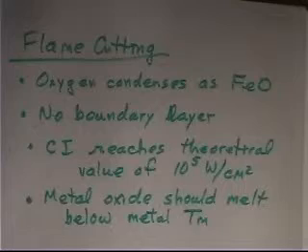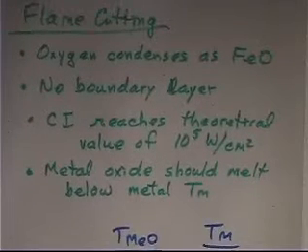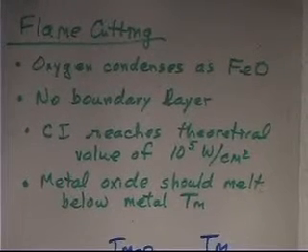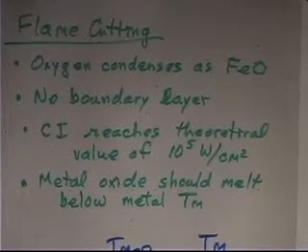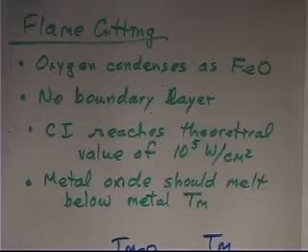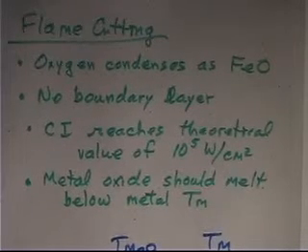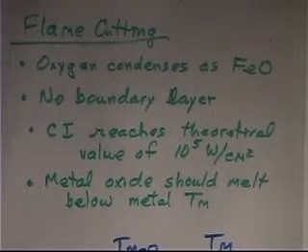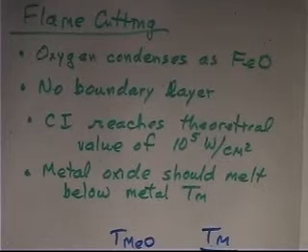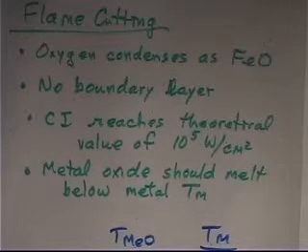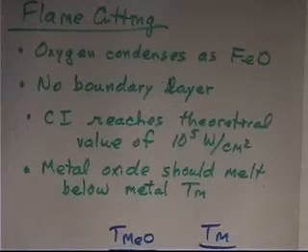And in this case, you'll heat up the surface of the steel to the point where the surface oxide just starts to either crack up or melt. So if we're talking carbon steel, it turns out the melting point of iron oxide is 1380 centigrade. The melting point of the steel is like 1536 of pure iron.